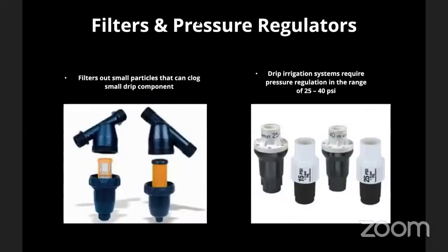If you are working with drip irrigation, you absolutely, not optional, need a filter and a pressure regulator. And this is one of the places where we see people go wrong quite a bit. At the Waterwise Community Center, for our local service area, we offer a program where we send a team out to assess someone's irrigation system, make a list of any efficiency issues or breaks that we find for them, a fix-it list, and recommend how they should have their irrigation system set up and their schedule to water efficiently.